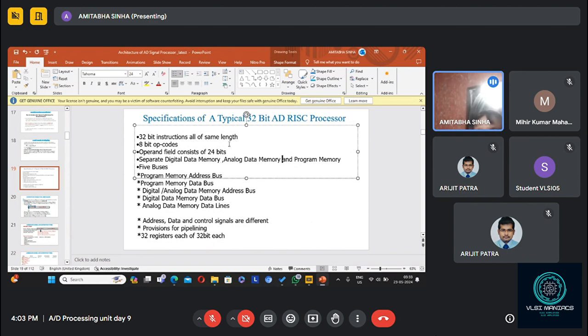Since here the data is of analog type and digital type, there will be separate digital data memory and analog data memory. So altogether there are 3 types of memory: digital data memory, analog data memory, and program memory. Because program memory is the same whether it's an analog instruction or digital instruction. They will be stored in the instruction format. Automatically there will be 5 buses.